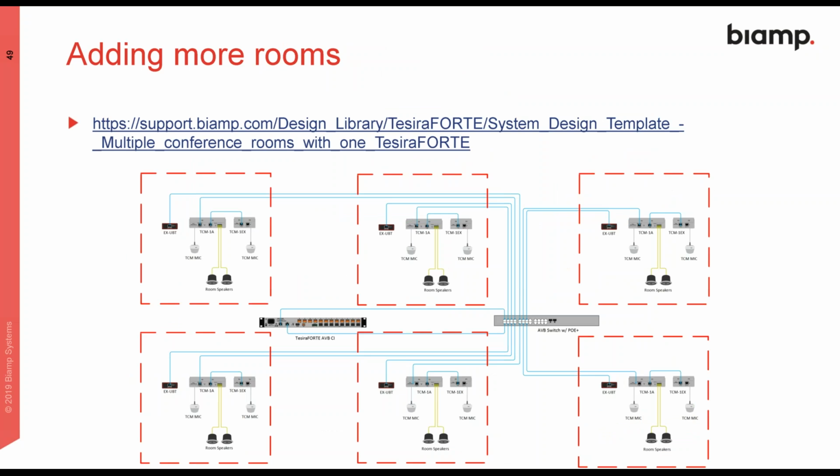So in this example, you have 6 rooms, each using the XUBT to provide USB connectivity in each room, or Bluetooth connectivity. Each of them has 2 microphones. And all that equipment is connected to a switch with PoE+ in this case, to simplify the drawing. And then you connect your DSP to that switch as well, and that DSP can process the signal coming from those devices.